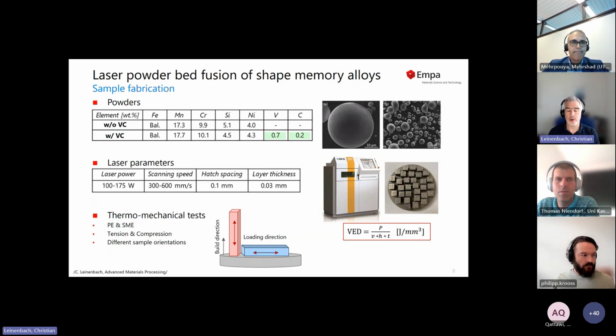I don't, although we do have a DED machine, an electron beam machine, but we have not put the powder into that. However, Elias did one experiment, and apparently it worked. They could fabricate the parts. However, the discussions that I also had with him is that the loss of manganese is much more pronounced because the melt pool lifetimes are longer.